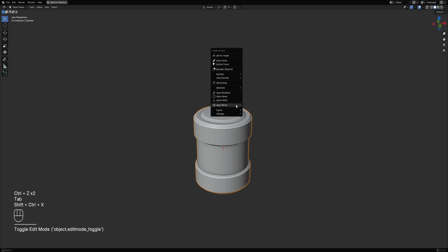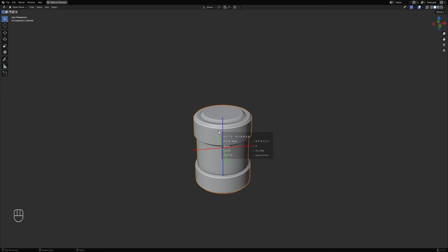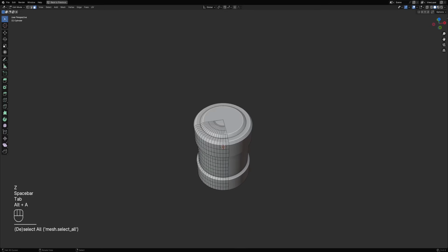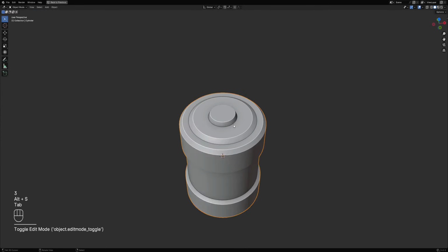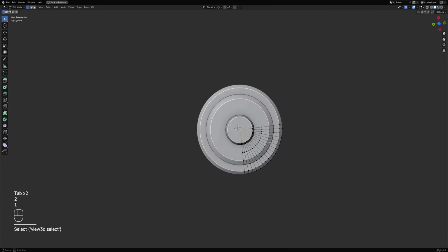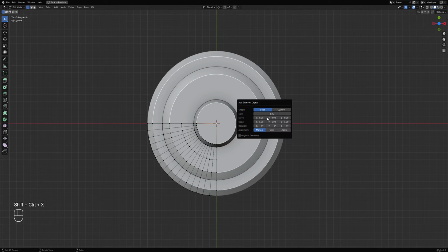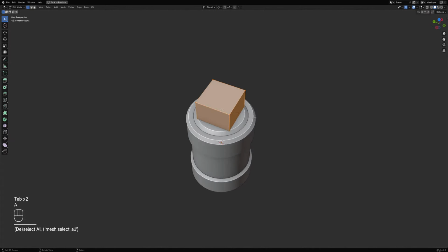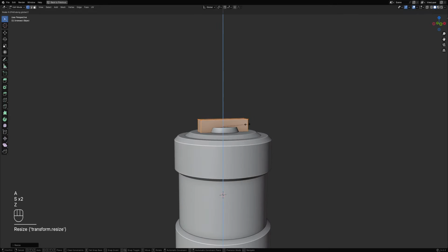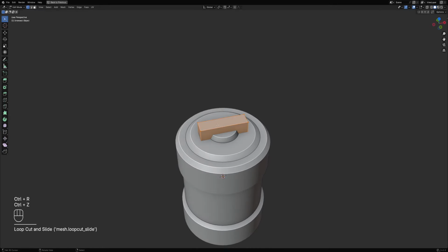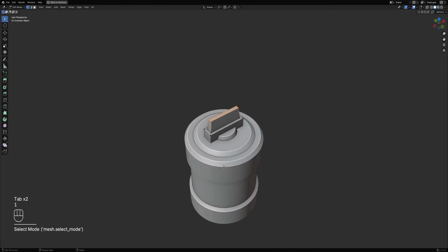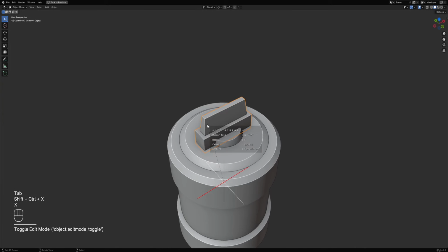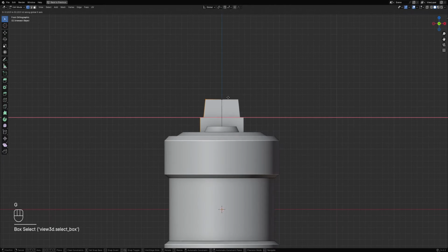Actually, let's get rid of the z-axis mirror. So we're going to put asymmetry in the z-axis and intersects cube. Mirror in the x and y. Going to scale this vertex center.